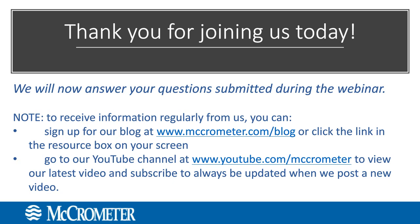Just based on the standard itself, there's a mechanical design option. So we can check if the meter can pass ISO via that. Or the second part of that ISO standard is a calibration over the full Reynolds number range, which we can do. Either we can try to do it in our own facilities, or we can offer third-party calibration. So it's really according to the customer need.